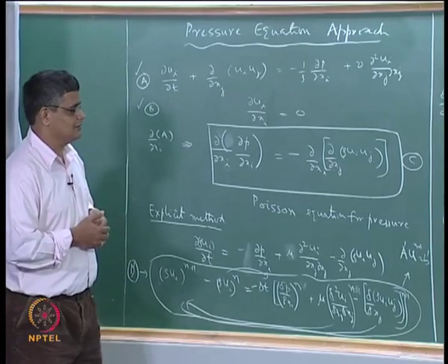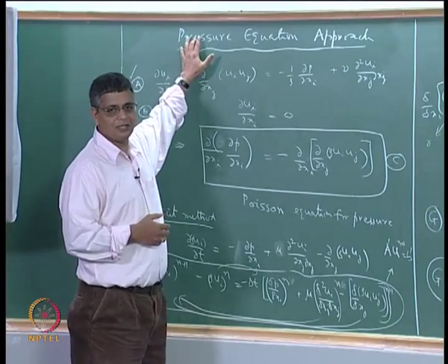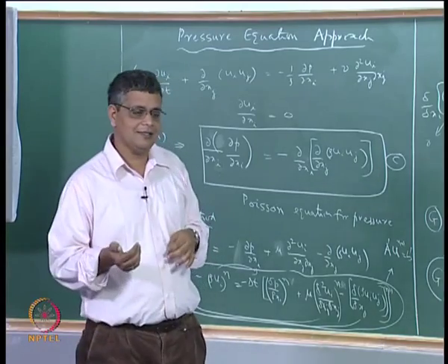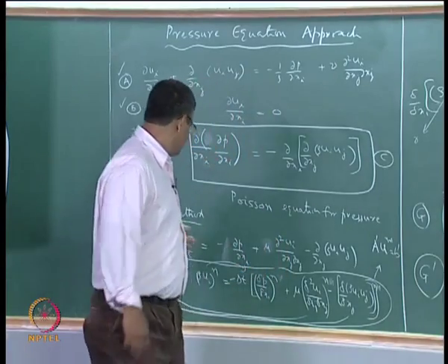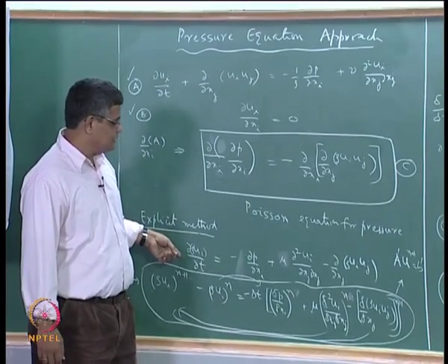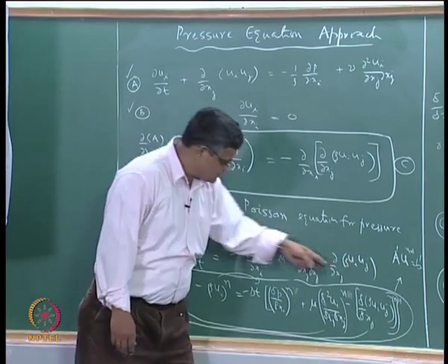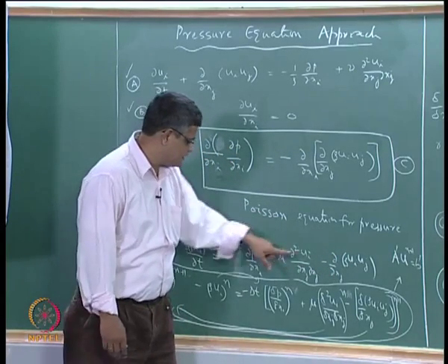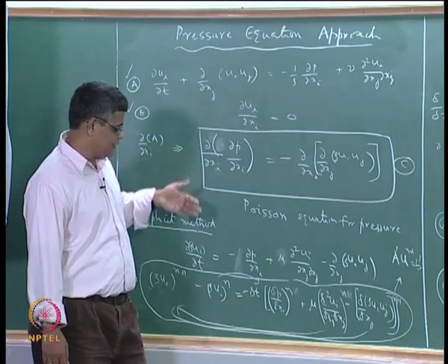So that kind of approach is used, and where we are solving not directly for the pressure but we are solving for the pressure correction. And what we mean by pressure correction is that with a guess pressure field we can get a velocity field from the momentum equation. Okay, so that velocity field need not necessarily satisfy the continuity equation, because in solving this with a guess pressure field, and for example using an implicit method here, we have not enforced continuity, we have not used the continuity equation or condition at any stage.